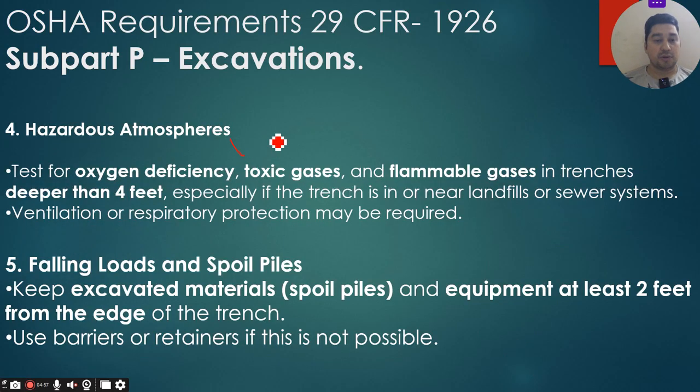Then the hazardous atmosphere, number 4. As per OSHA, tests for oxygen deficiency, toxic gases, and flammable gases need to be done in trenches deeper than 4 feet. So there you have to conduct a test.